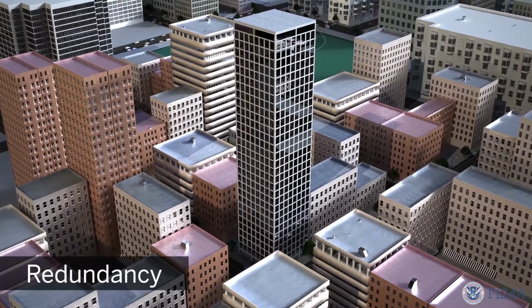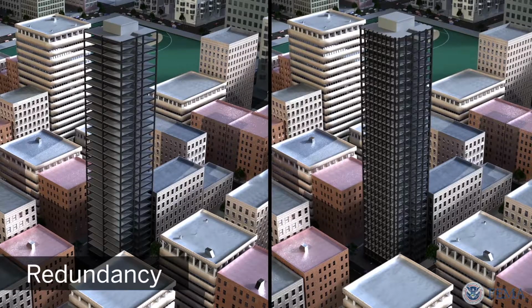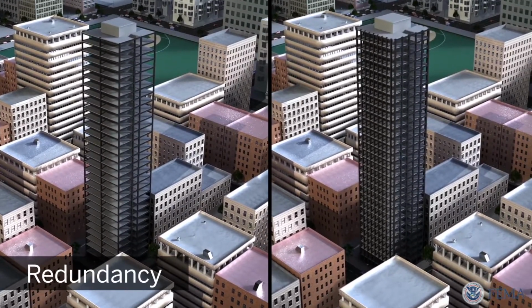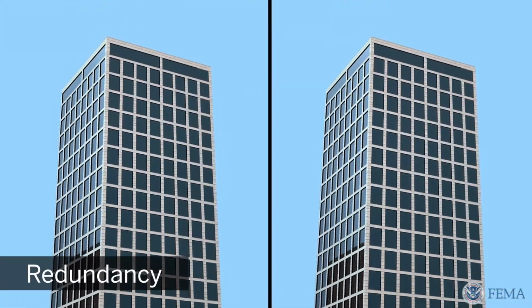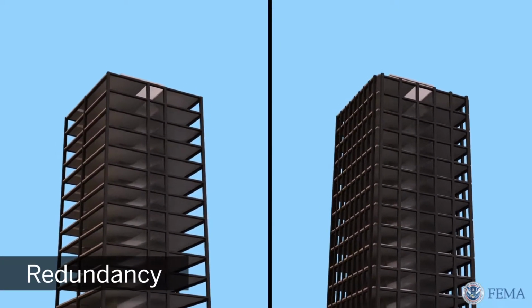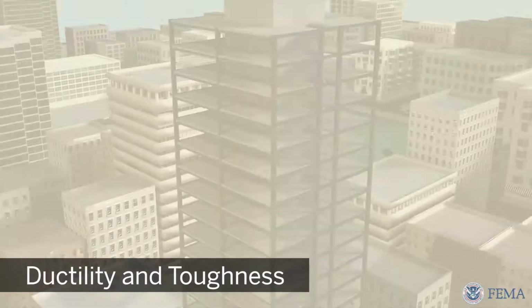If all of a structure's strength and resistance is concentrated in only one or a few elements, the structure will not have the necessary residual strength if these elements are seriously damaged, and it could collapse. If a structure is redundant, a relatively large number of elements participate in providing a structure strength, and, if only a few are badly damaged, the remaining elements should have adequate residual strength to prevent collapse.